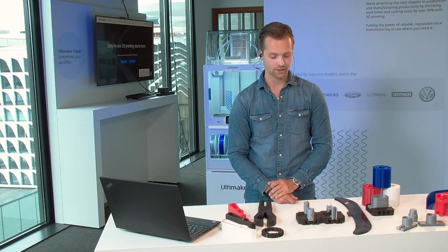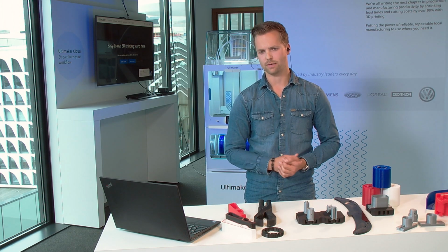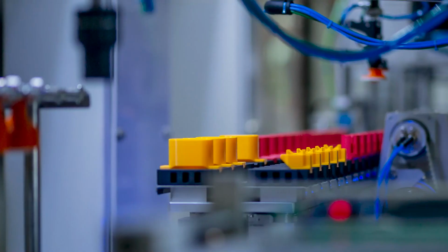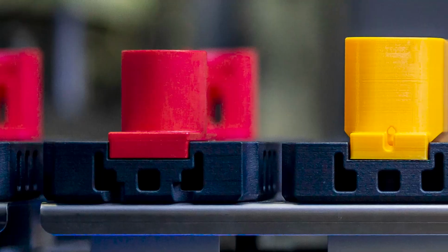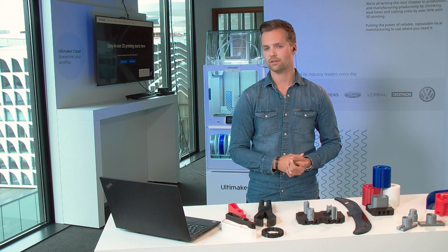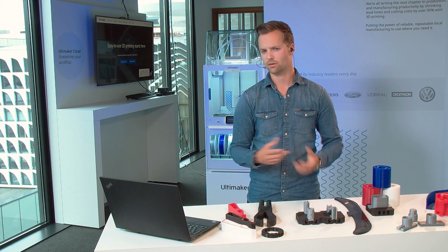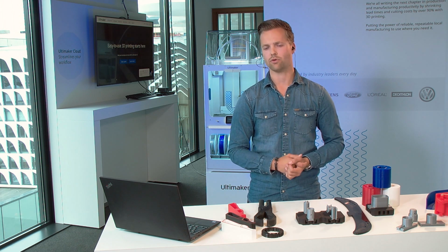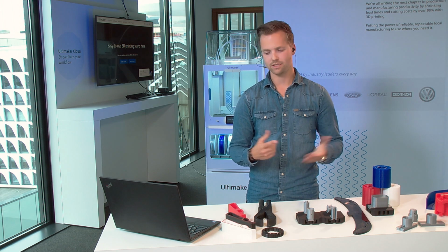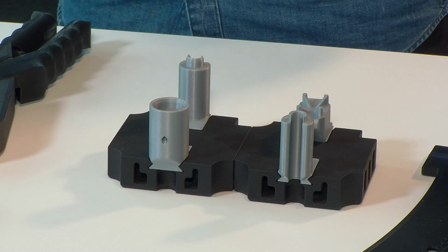Different than this is also color coding. So if you want to switch, for example, to a different format, they use different kinds of colors. So if you ask somebody to change this production line to run color number red, they only have to change the colored part to the color red, and then you can already set your format to that kind of batch you want to run. So it can be as easy as that. It's a really poka-yoke solution, but really high value.